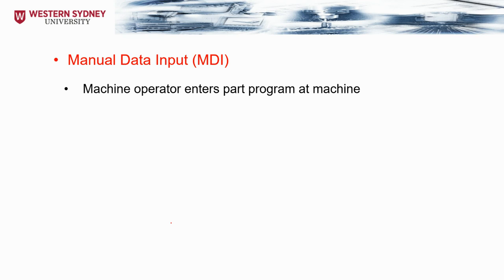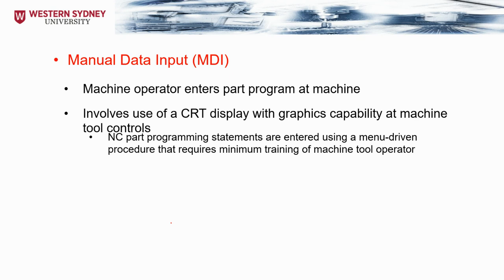Now the other method is the manual data input, or the MDI. The machine operator will enter the part program into the machine. This will use the CRT display with the graphic capability of the machine tool controllers.